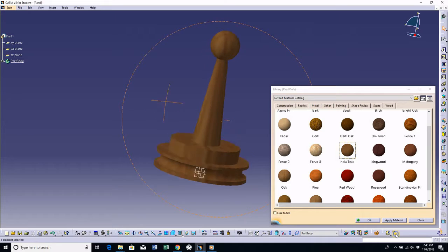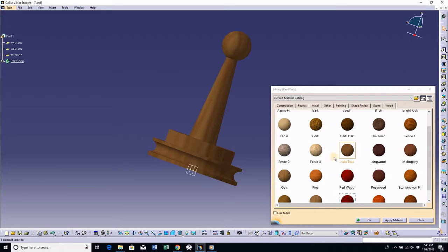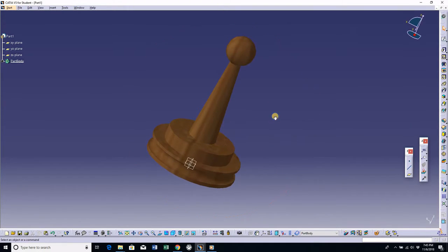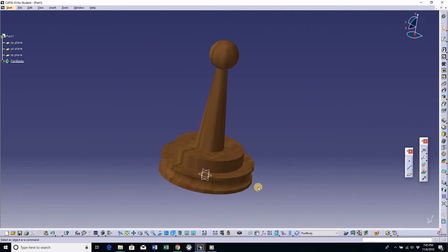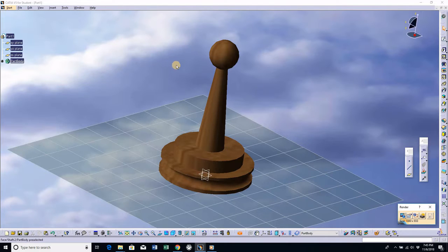So once you're done, click on OK, and if you want to get a 3D screenshot of this, we can use the Photo Studio Easy Tools right at the bottom of the screen. On the bottom toolbar, select that, and we can change the background, and you can also customize the background of this screenshot.